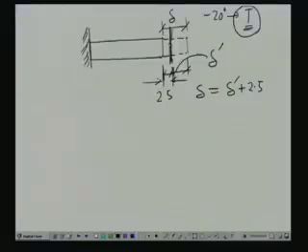So, when I have removed this particular wall and allowed the bar to move freely, naturally the second consideration, which is the realistic situation, is that I will have to apply some force on this bar and bring back this deformation to this particular state, so that the member is between these two walls.